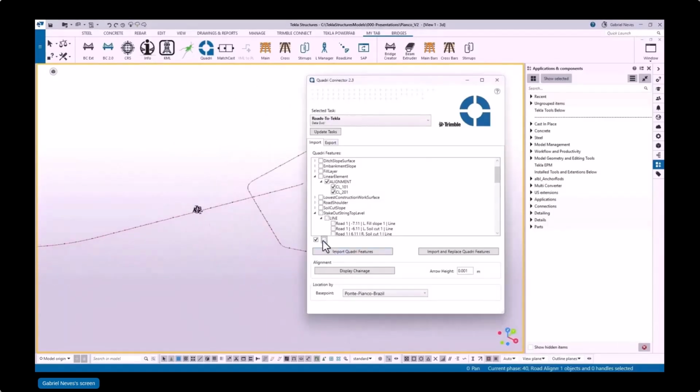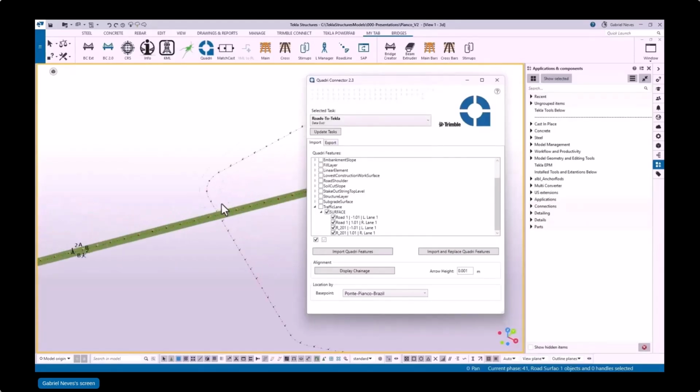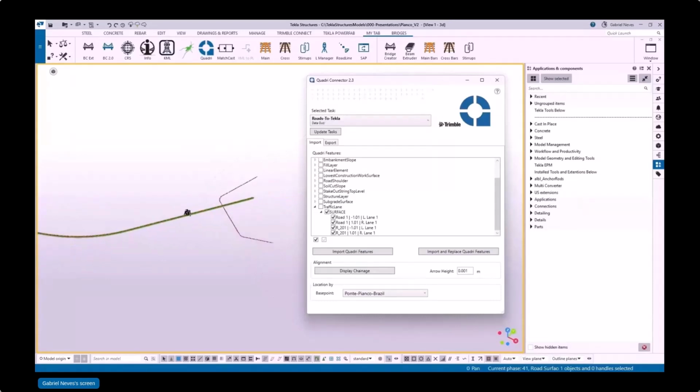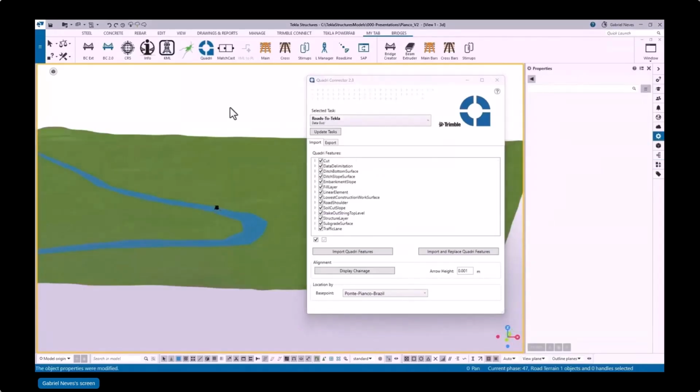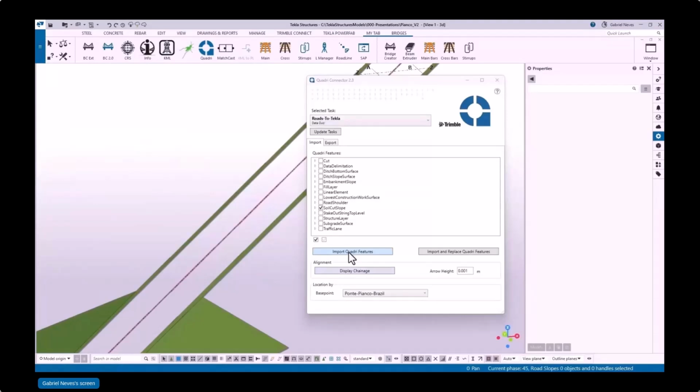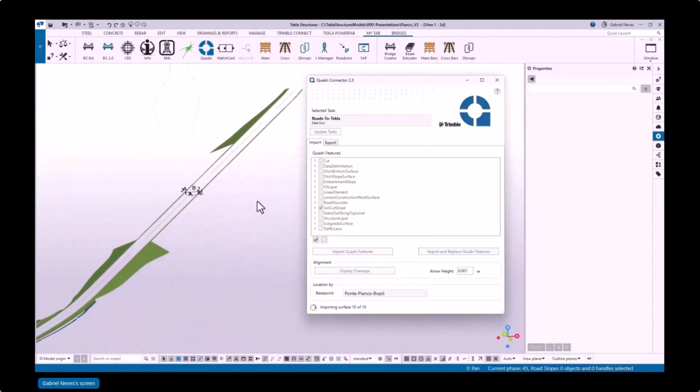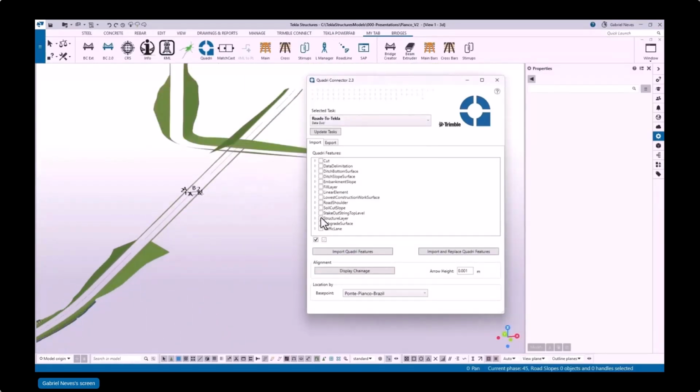Let's see if the video shows bringing some more data. For instance, if I'm doing an underpass and if I have the slopes, and I was doing that many, many years ago, in the past we would do cross sections just to define the wing walls. And from the moment we have 3D data, we just place the wing walls just looking at it and moving up and down or opening the angle of the wall. So that is why the slopes are important.